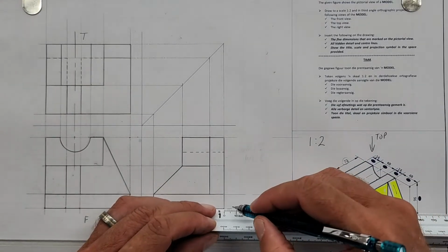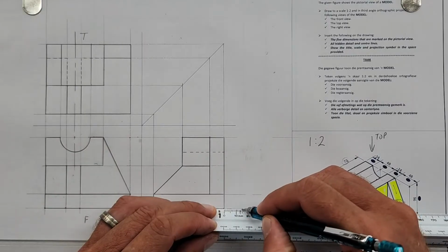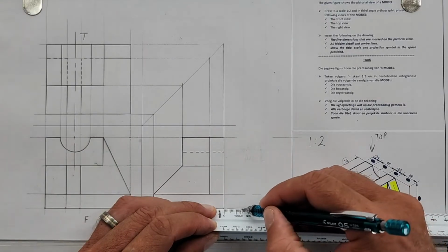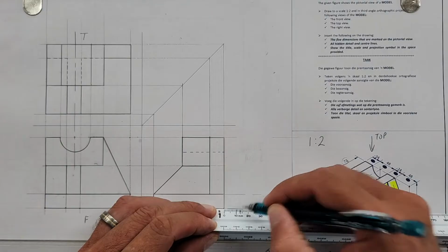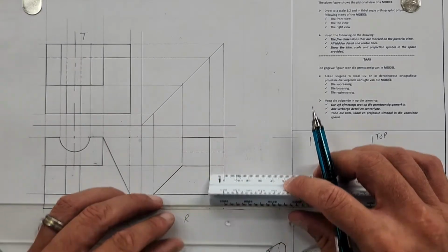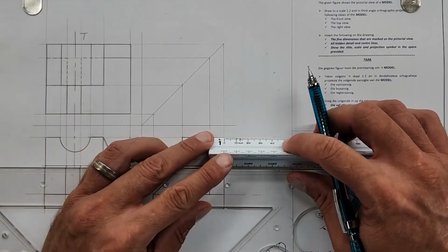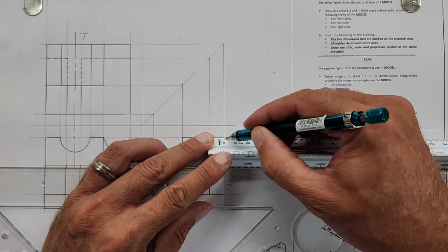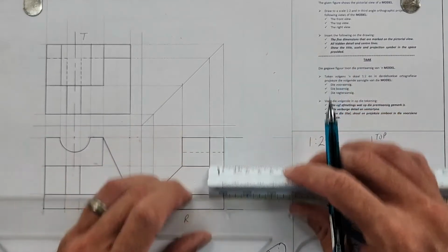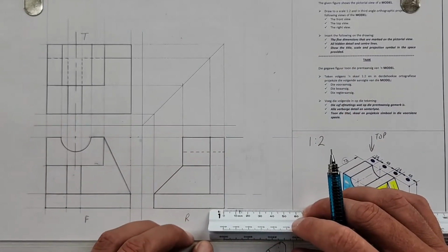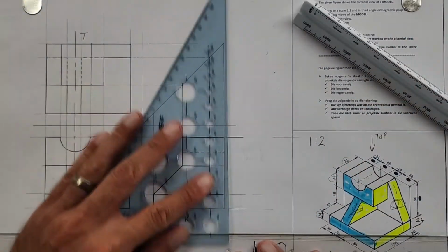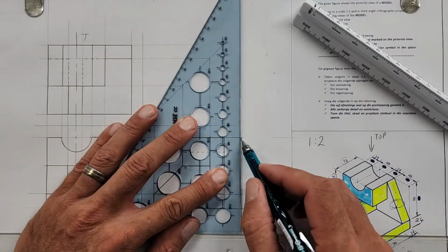First 2 millimeters you keep open, and then you do a line of about 15. Alright. So up to about 15 millimeters. You can slide that up and do exactly the same on the top. 2 millimeter gap and draw again up to 15. Okay. And then the dimension line goes in there.